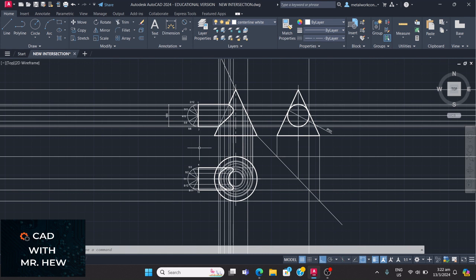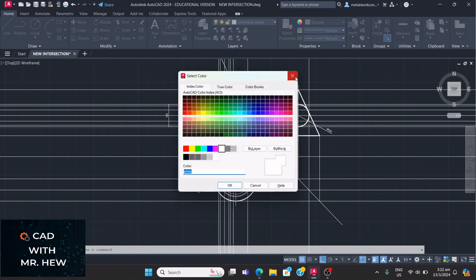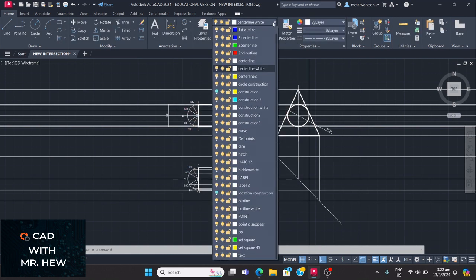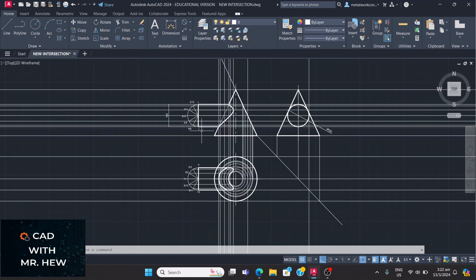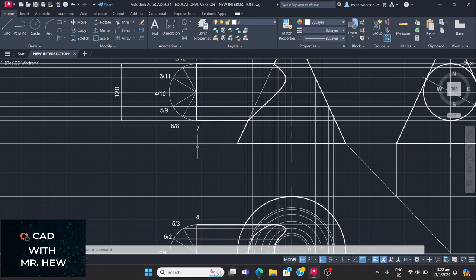What we're going to do is draw a construction line. So I'm going to change this layer to a construction line layer, which I use as a default layer in AutoCAD, 0. It would be better practice to make a layer called construction rather than using the 0 layer, but maybe next time I'll make another layer specific for the construction line. So what I can do is drop a perpendicular here. This will be the last point, right? This will just be construction.